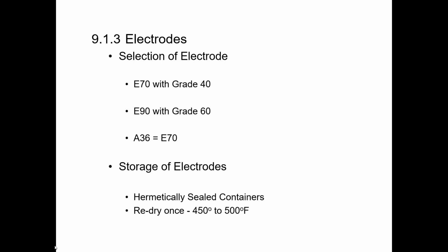If you don't know what a full penetration butt weld is, it means you have two bar ends, one end touching the other, and you prepare the end of that bar by grinding it, almost like sharpening a pencil, not quite that extreme. You put those two together, and then fill that with weld. That's the full penetration: the weld is penetrating the full thickness of the base material.